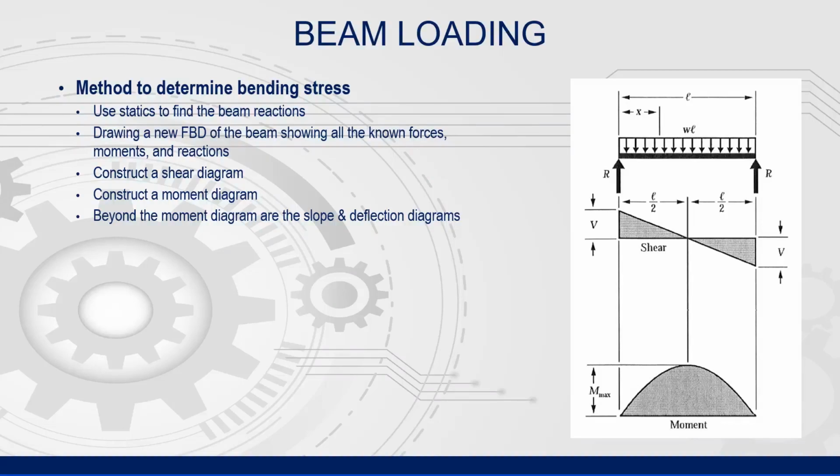A common mistake made by students in finding the maximum moment is the assumption that it is the force applied times the length of the beam. That is only true for cantilever beams with a single load at the end. If you check the beam table references provided, you will find that each load and support has a different formula for maximum bending moment. But not every situation is covered in the reference tables. However, with the graphical method, you can solve for maximum moment for virtually any setup.